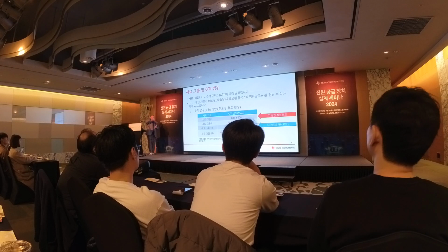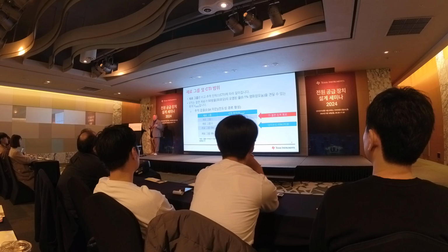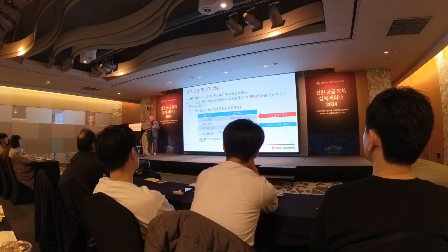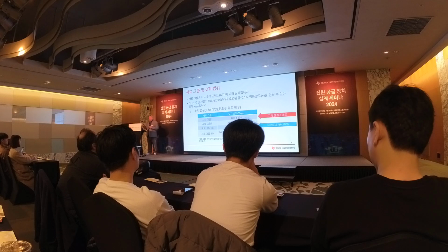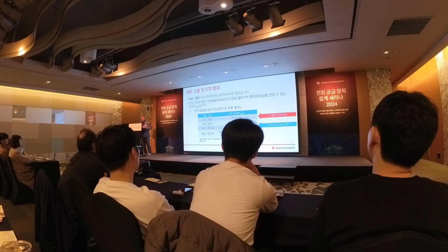So I'm applying a high voltage across my board, I'm dropping this contaminated liquid onto the board, and I need to see how much I need to raise the voltage by before it starts to provide a conduction path. So as long as the current stays below 0.5 amps, I'm going to keep increasing the voltage.